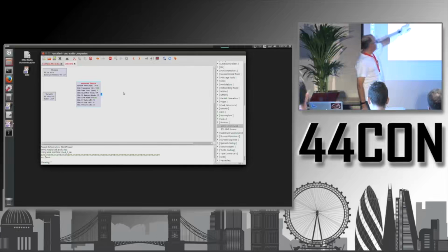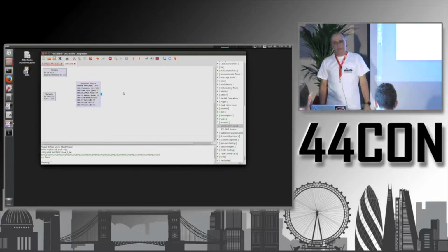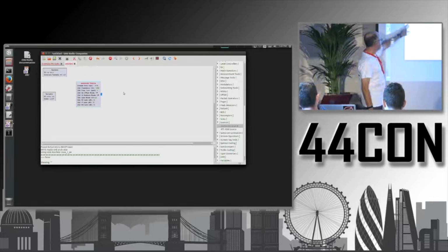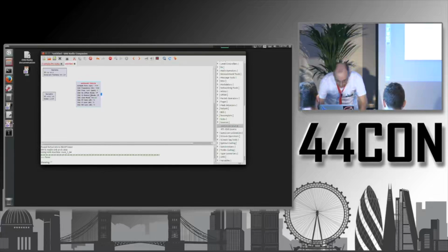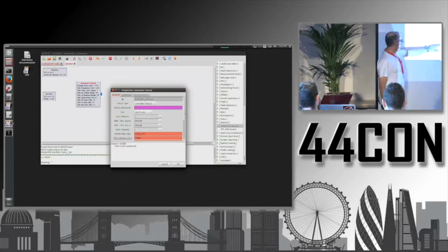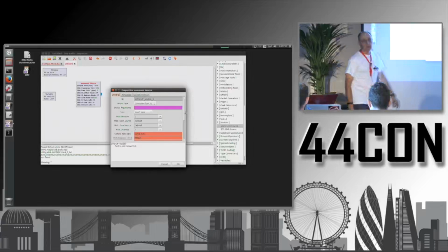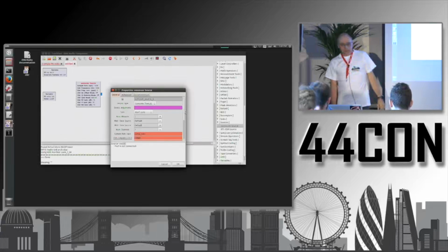And then you can see your sample rate, which is 1.92 megahertz, the value that we gave it with this variable. If you double click on it, you can see the sample rate is not a number but a variable, the variable that we defined here.